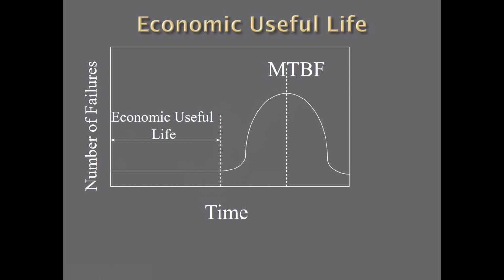You know, the failure rate of V-belts, for every 18-degree rise, you cut the life of the V-belt in half. Is that V-belt in an enclosed guard where it runs hot? Lots of questions we can ask because we always want to extend that economic useful life.